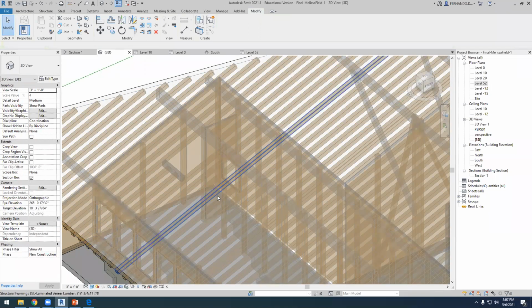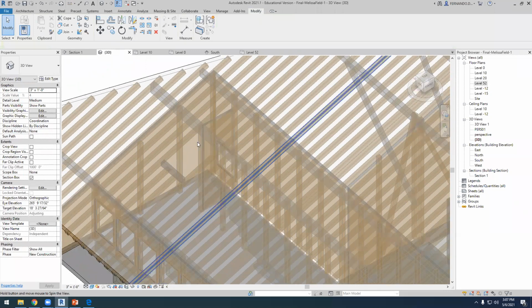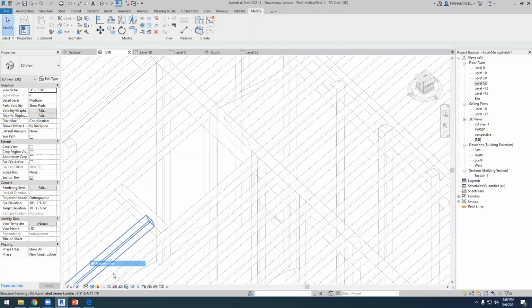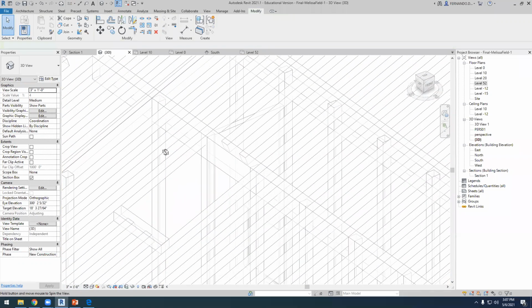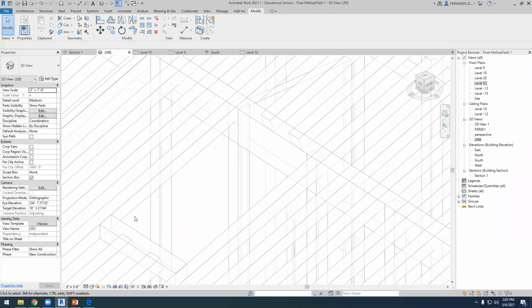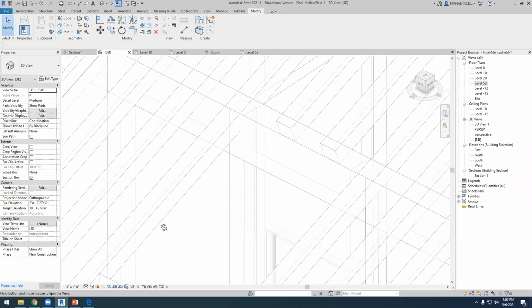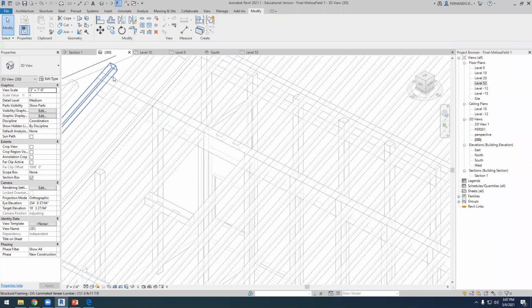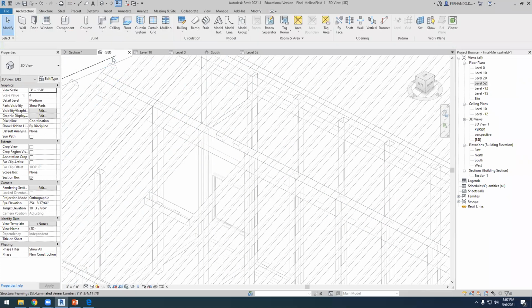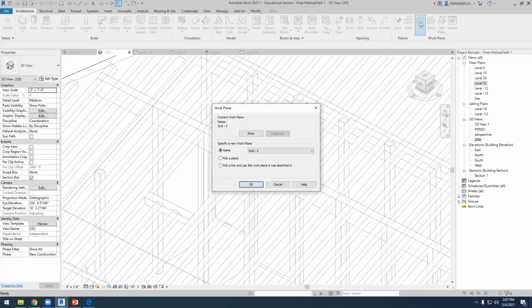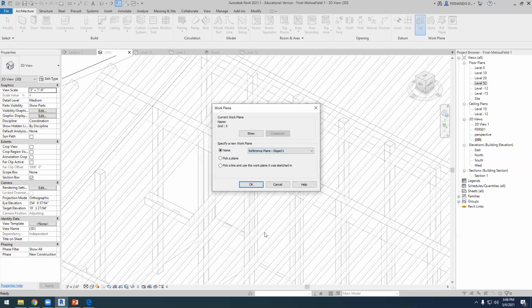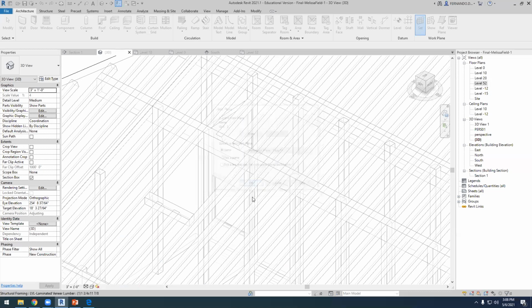So we're on the 3D model. We are, I think, yeah. This is less confusing, maybe, or more, I don't know. We are going to work with architecture. I'm going to set this on slope 1 because I want to draw something on that plane. And I'm going to work with model lines.